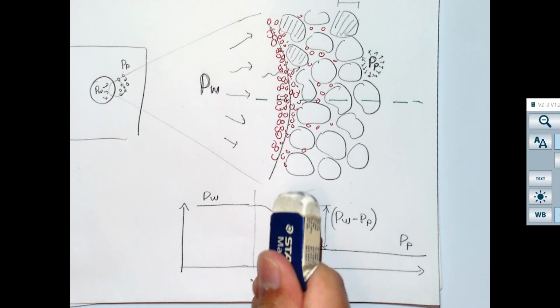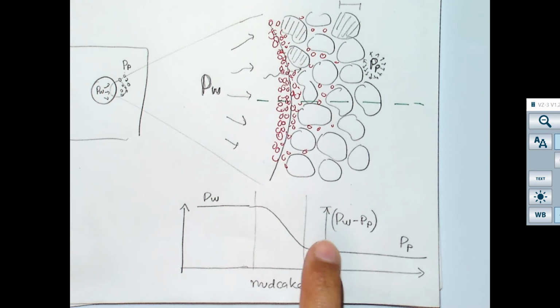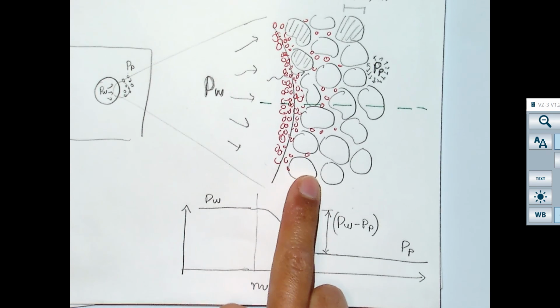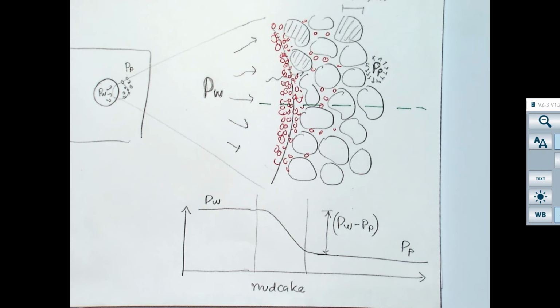So these forces can be very strong, and they add an effective stress to the wellbore and add wellbore support. And that, as we're going to see, is going to be very important for wellbore stability. Okay, so now let's put everything together.